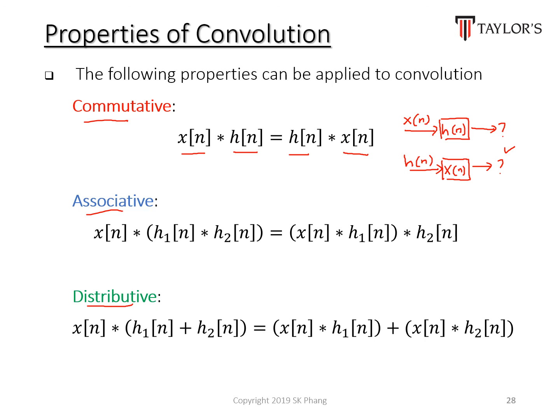So earlier on, when you do convolutions with one signal and one system, you can actually do it the other way. So you can actually reflect signals instead of reflect systems, and then you do the graphical methods. Or in method number 3, when you have the tables, you can actually write the systems on the left column instead of on the top row.